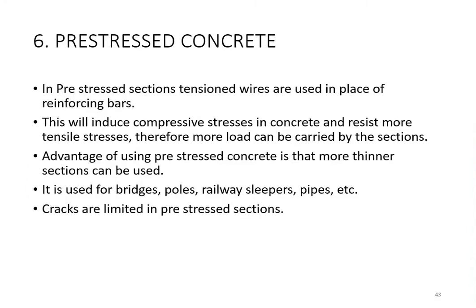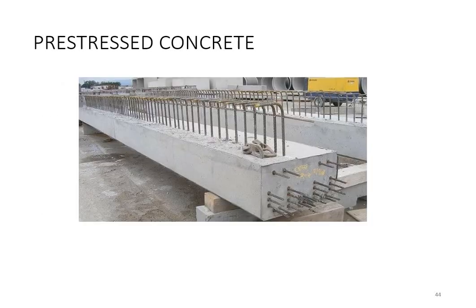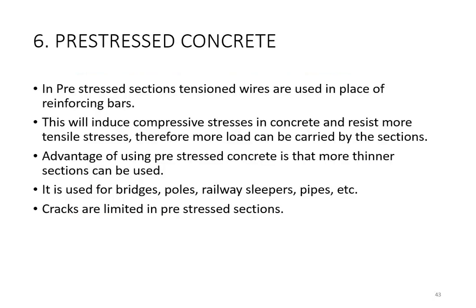Next you have the pre-stressed concrete, which is being widely used. All the beams or girders which you have seen in the metro pillars or in bridges, Palarivattom bridge, flyover bridges, all of them you can see are pre-stressed concrete. You might have seen such bolts coming out of this. In pre-stressed concrete, what you do is you tension steel wires which are placed inside the concrete. It is not the reinforcing bars. You have tensioned wires inside that.